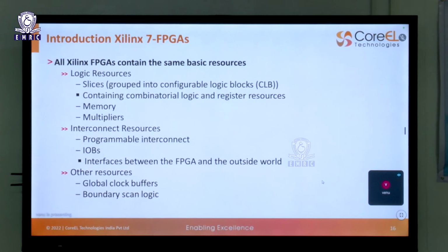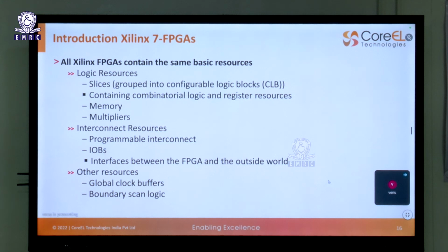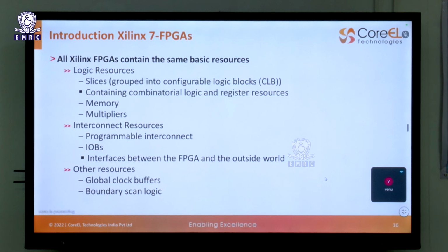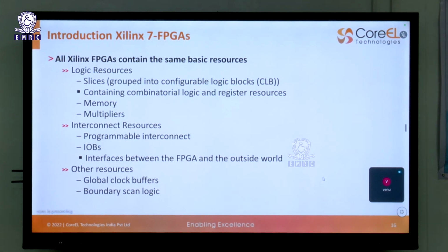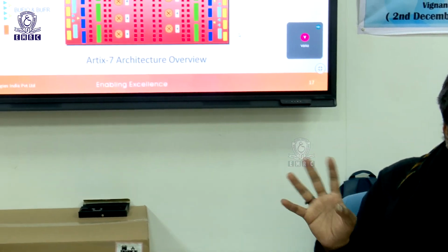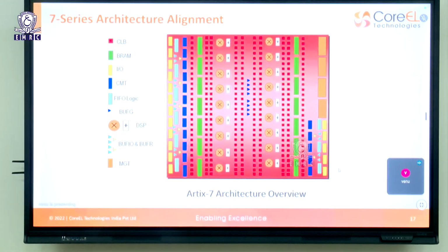The next thing is there are a few more resources that are required for us on the board. Okay, they are not going to be something that we can completely access and reprogram. They are going to be some kind of resources that are purely taken care of by the tool or the board itself. So this is a set of resources that we'll definitely have on all the 7 series architecture based FPGAs. Okay, here we are purely talking about a pure FPGA. Okay, we are not discussing an SoC here.